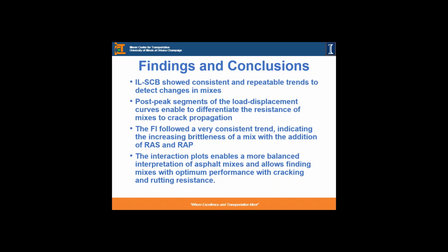Overall, the findings and conclusions from this study are that, with the test developed in this study, we really see some consistent and repeatable trends to detect changes in the mix, even though they were nuanced. And the post-peak segments of the load displacement curve really told a story about the mix's crack propagation resistance, which we exploited to develop this flexibility index. And the index that was developed followed a very consistent trend, indicating the mix's increasing brittleness with the addition of RAS and RAP.